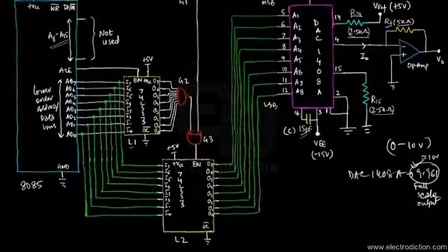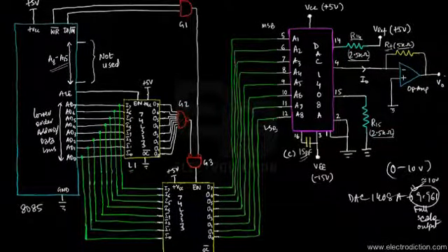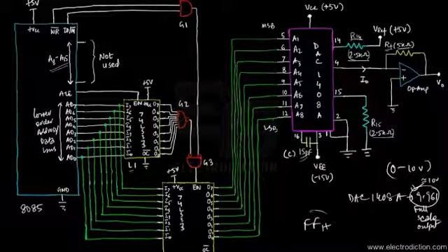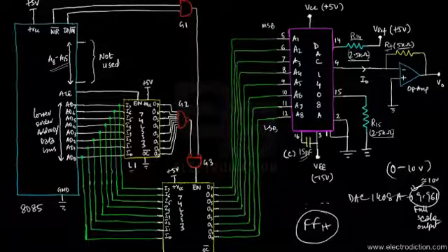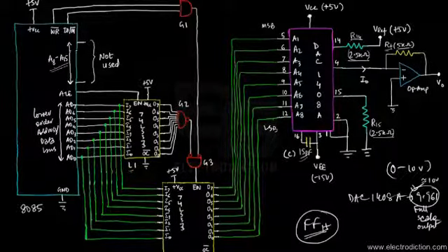Keeping that in mind, let's check the circuit, whether it works off the address FFH or not. Let's say we have a code written in our program for the interfacing of this hardware. Whenever the 8085 sends out the output port address FFH from its lower order, since the port address is just 8-bit data, we've used the lower order address data bus. We've not used the higher order address buses, that is A8 to A15. You can see that they're unused over here.